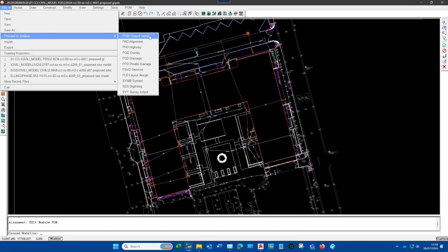And so that's what ground modeling is. And it's also used for interrogating that surface mesh. So you're using it to figure out the contours of your site. You're using it to cut the sections of the site to compare existing and proposed ground levels. You're using it to get your volumetrics of soil and pavement materials. So that's what you're using the ground modeling for. You don't use it for your roads. That's what the next three are for.